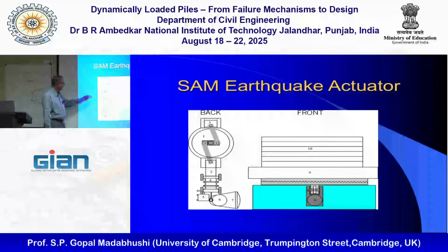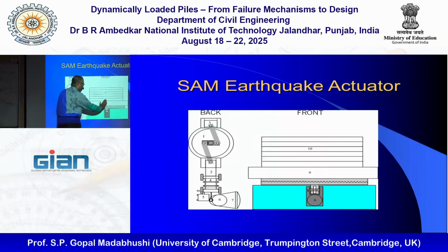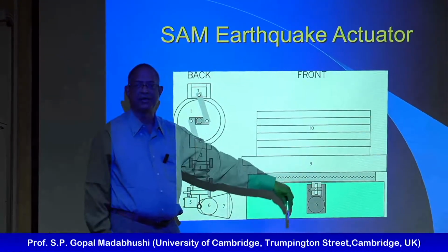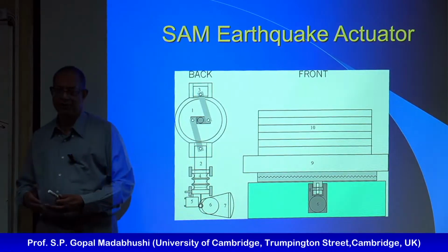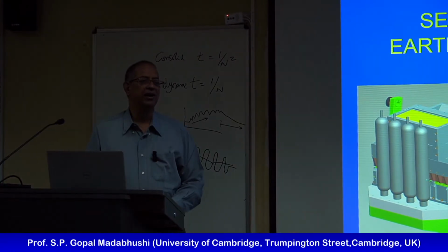So all it is, as I said, set of flywheels. We oscillate the reciprocating. You run this motor. It's like the old choo-choo train, steam engine, right? So you convert rotary motion into reciprocating motion, and the clutch basically engages the rod. It's very straightforward. And once this is twisted, this twist here makes the table shake back and forth. And because I can adjust the pivoting distance between here and here by using a three-phase motor, I can get earthquakes of different amplitudes as well. That is the cheap and cheerful earthquake actuator.